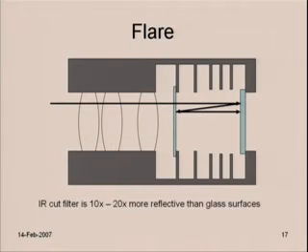So it gets worse. Not only do we have a sensor back there, but we usually have an IR cut filter. So the issue here is that the dyes, these little spots of dye that sit in front of the pixels that color them red, green, and blue, don't absorb infrared or ultraviolet light. Ultraviolet light is a little bit of a problem. Generally, the glass in the lens stack itself is absorbing some of that for you. A much bigger problem is infrared.